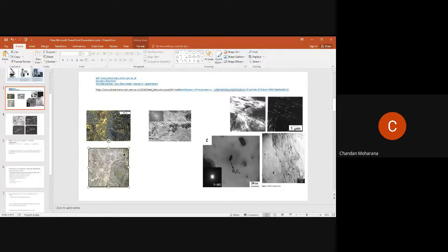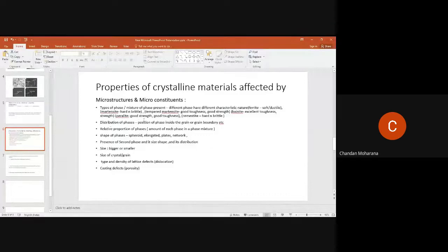That is okay. Or you can do spheroidizing heat treatment, which I will discuss later. In spheroidizing heat treatment, this network of cementite becomes spheroid, spherical size particles, uniformly distributed throughout the material, right? So now you understood how important the distribution of phases is and how it affects the property of steel or material. Is this okay now? Yes, sir.